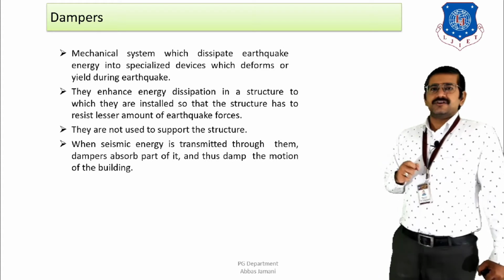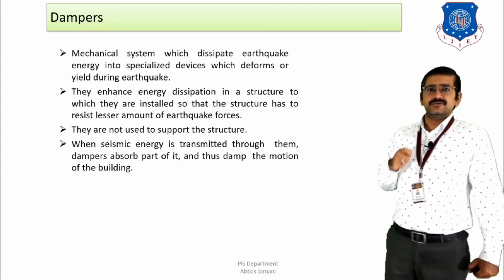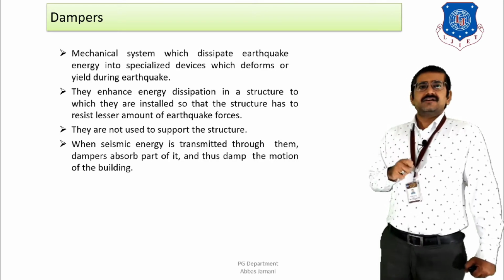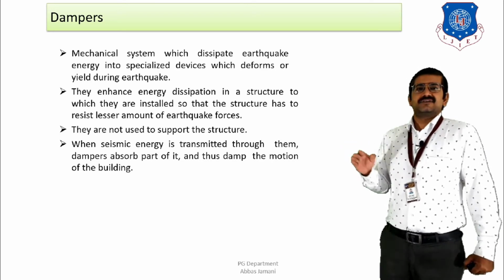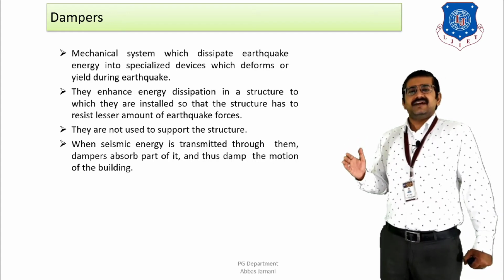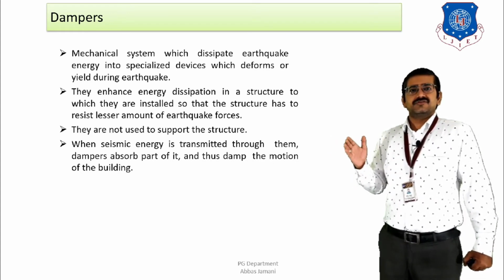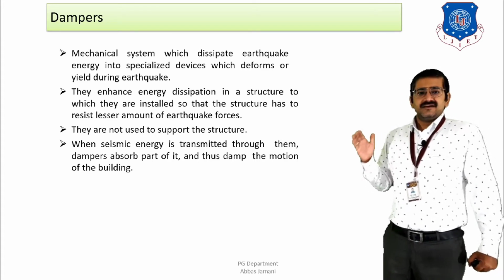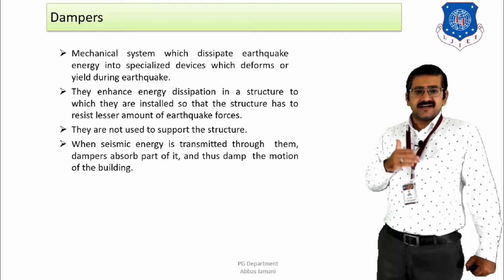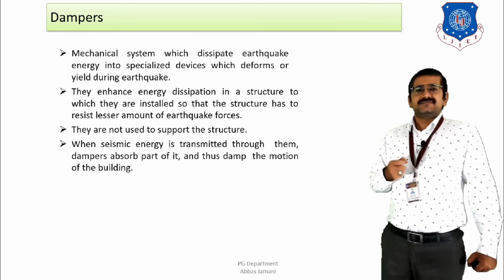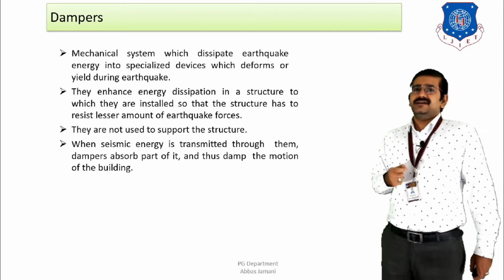Right? Now what is going to happen is that when these devices are used, they will enhance the process of energy dissipation, and as a result, a lesser amount of force will be transferred to the actual structure. When a lesser amount of force is transferred, the deformation of the structure is also going to be controlled to a great extent. Right? And lastly, when seismic waves are transmitted through them, these dampers absorb a good amount of energy, and that is why the motion of the structure is also going to be dampened.